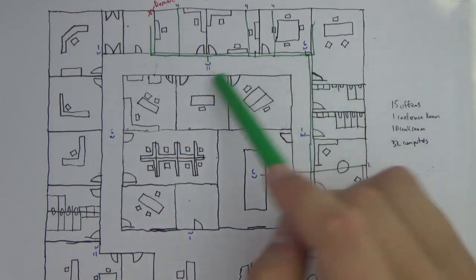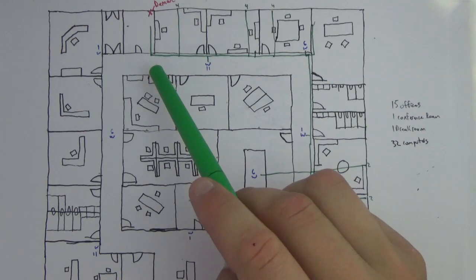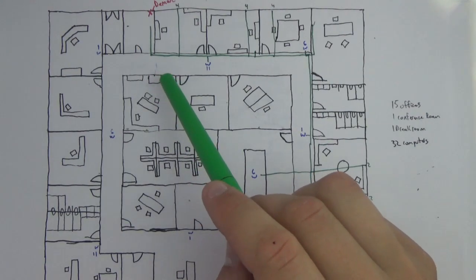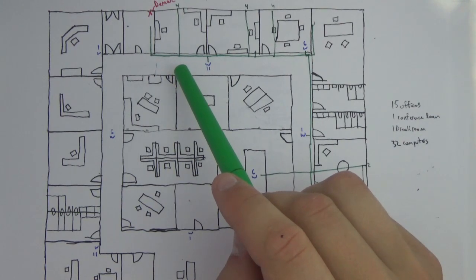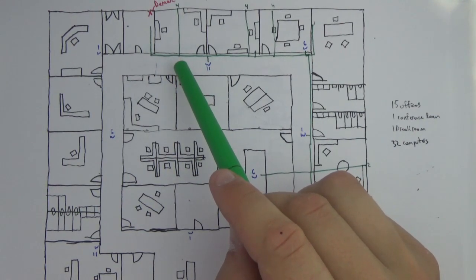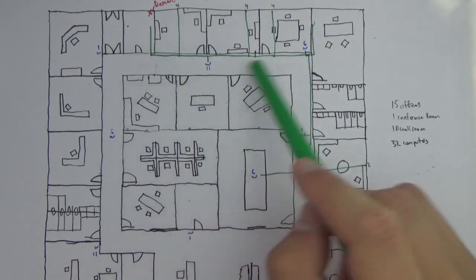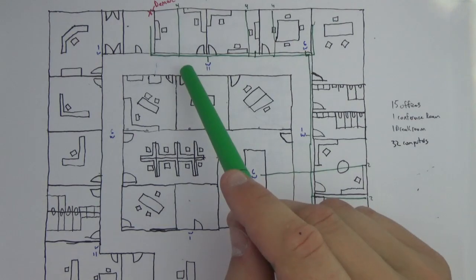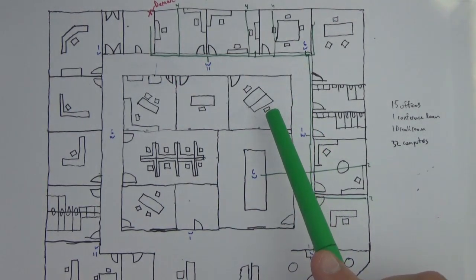If we're pulling these through piping, you've got to be careful about how much force you put on the wire. If you put too much force on the wire, you can actually stretch the copper inside of it, or you can actually twist it and cause it to break. And if you break one of those wires, it doesn't matter what you do on the endpoints, it's not going to conduct an electrical signal. So you want to be careful when pulling it, and you definitely want to test it to make sure that each of those runs are good on both sides.